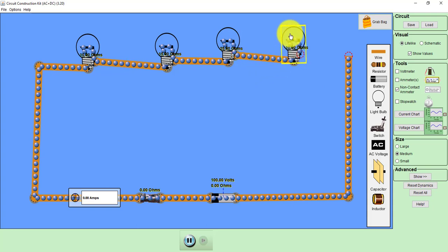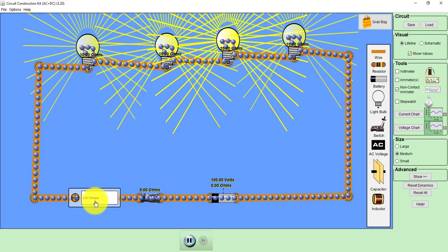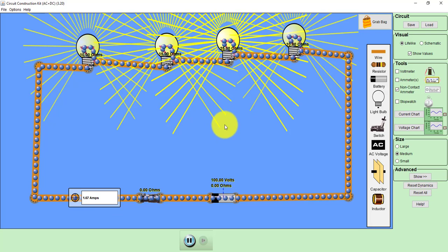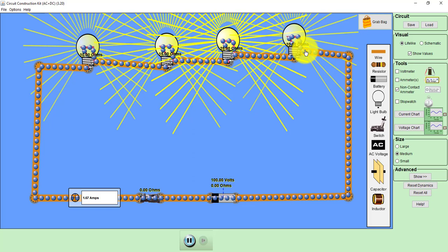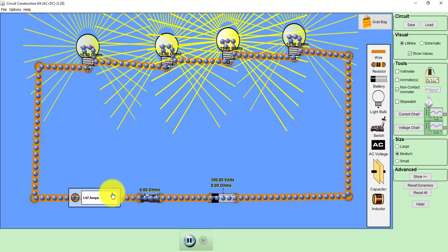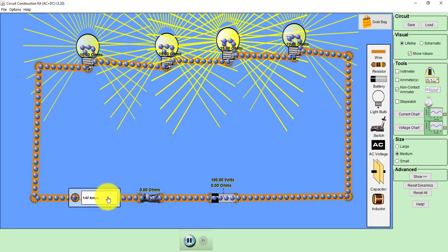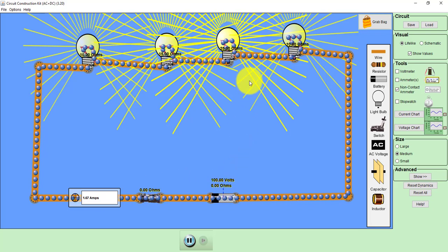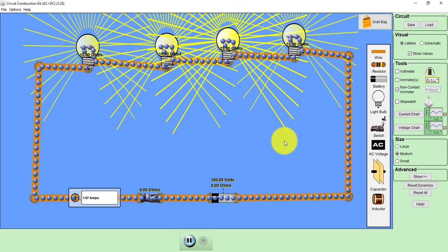How was the earlier current? If you remember, it was 2 ampere. Now if I go on adding the resistances, current will go on reducing. So as you can see, current has reduced from 2 ampere to 1.67 ampere. Reason is obvious. As you go on increasing the number of resistance in series, equivalent resistance will go on increasing. So therefore, the current will reduce, because by Ohm's law, total current or the supply current is voltage divided by equivalent resistance. Okay. So these are the various characteristics of series electric circuit.